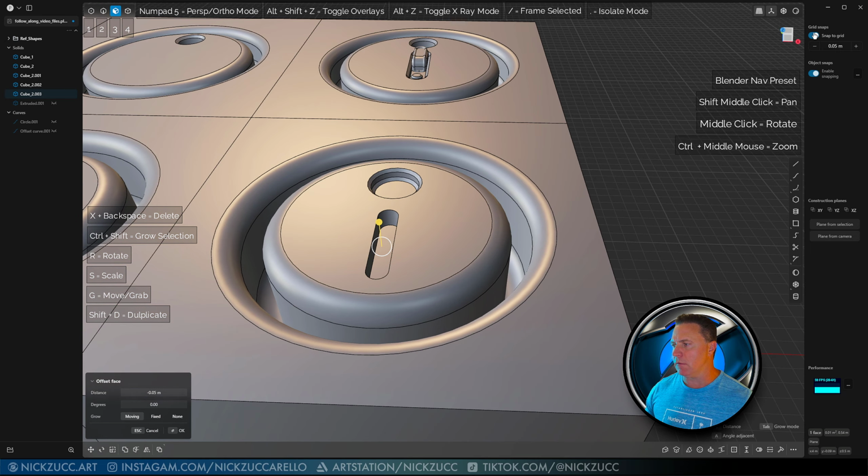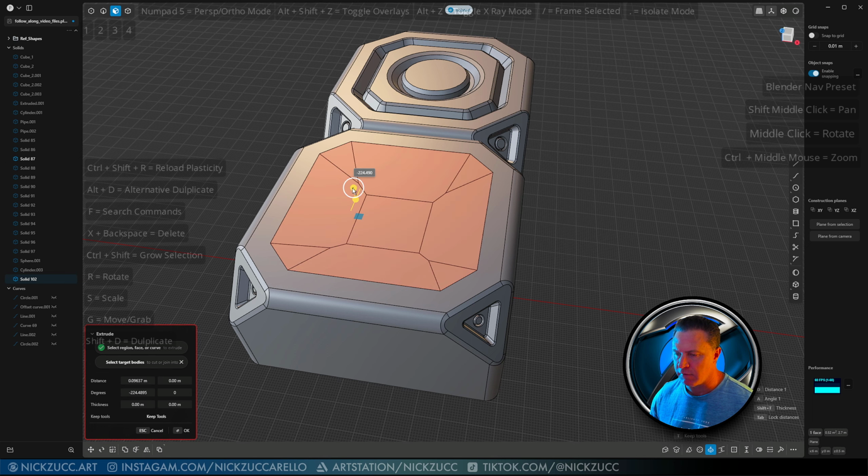All right, so now we can select this top face. We'll do 3. We'll do O again to offset this, get some kind of distance going somewhere in there-ish, right there. And again, I like to do this inset thing. So if we just click on that face with 3 and then push in, that's going to offset the face, but I just have not had the best luck with this. If I select this, I pull it down and I do this degree thing, it'll do this inward thing. If I go out, it's kind of ruining that shape that I have. So that's where I found if I just select this, tap E, drag down, and then I do this, that works. The only thing is that if it goes too far, it ends up failing. So just be aware of that.